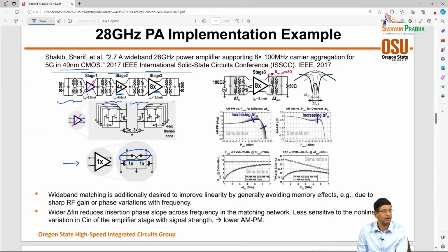So you neutralize a unit cell, and then we take this unit cell and we build the PA with that. It depends upon particular design approaches, but the general idea is usually to take a unit transistor, do all the layouts, everything on it, do an extraction so that there is an extracted model for this unit cell transistor, right.